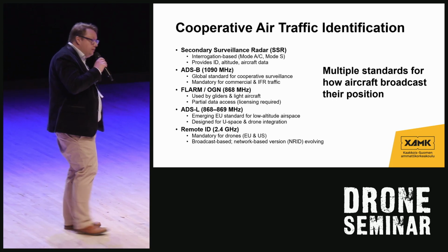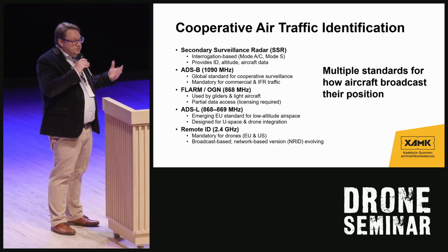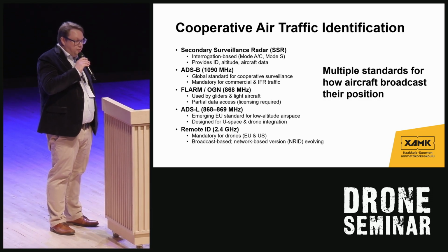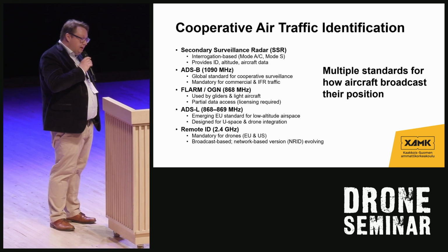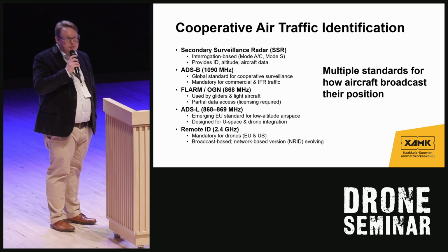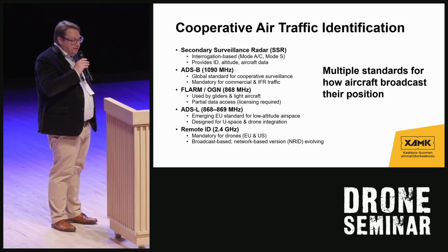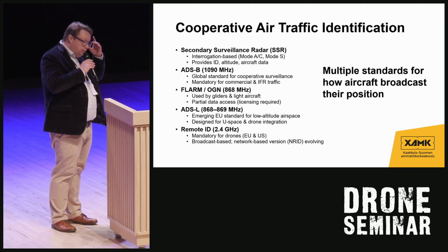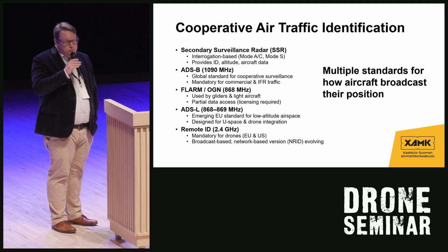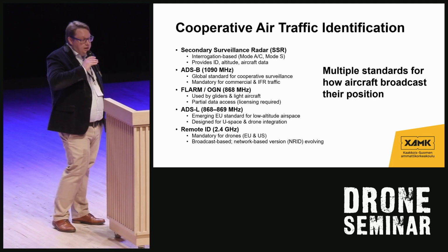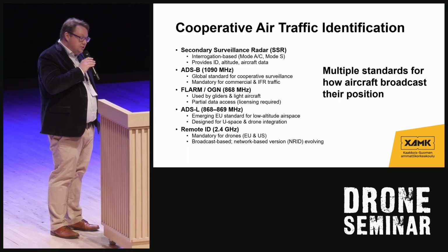They just have a wide network of ADS-B receivers which receive these position reports from commercial aircraft. Because ADS-B is standardized, it requires a permission, and it requires a certain amount of power. So maybe this is the reason why ADS-B at the moment is mostly reserved for commercial aircraft and maybe for those higher-end private aircraft.